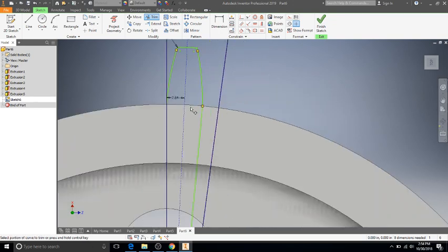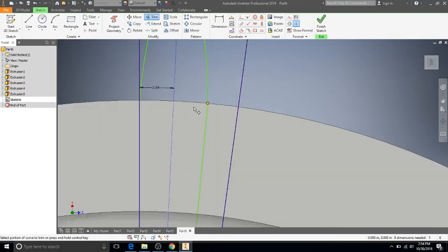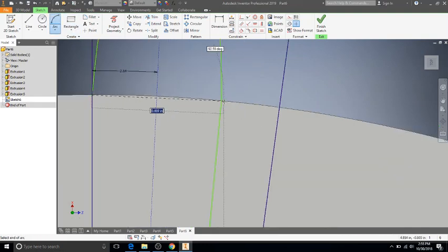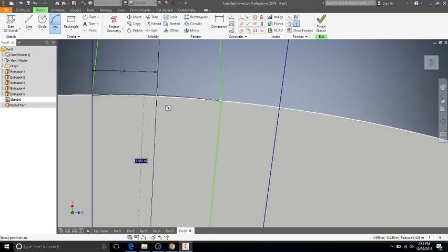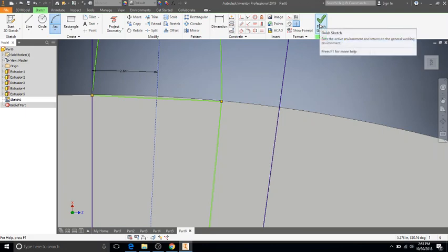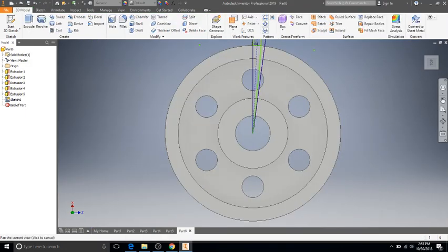Okay. Oh, you know what we don't have is the bottom piece here. So let's see if we can get an arc to snap to that top. We need an enclosed shape in order for extrude to work. It's wanting to go above the line. I'm just going to make it inside so it's a solid piece. It doesn't matter. Should be just fine. Okay, super. Zoom to fit.